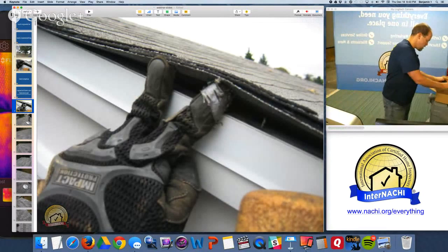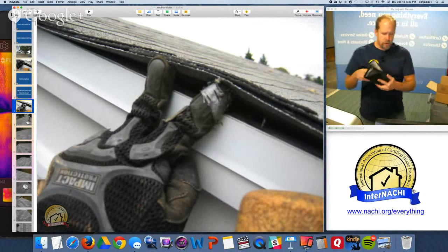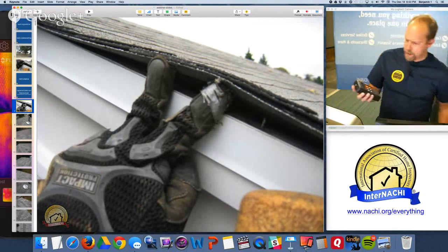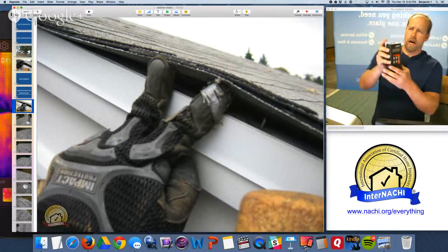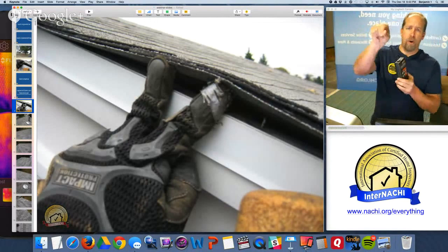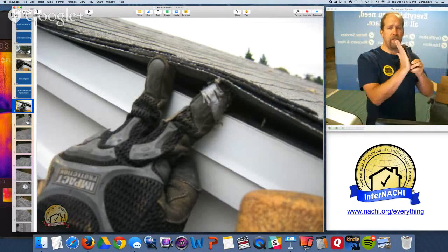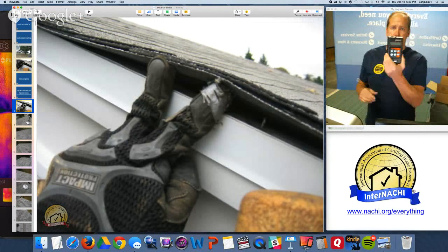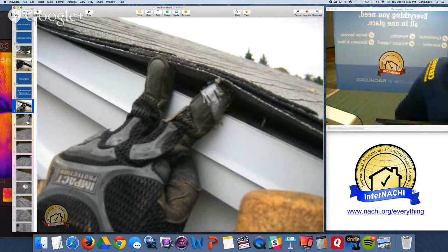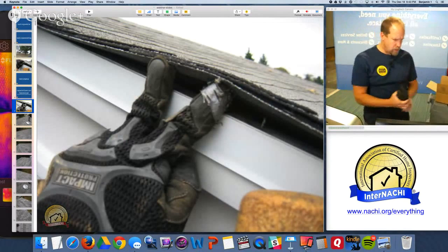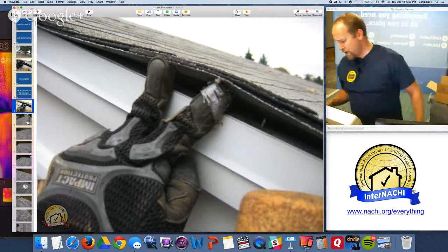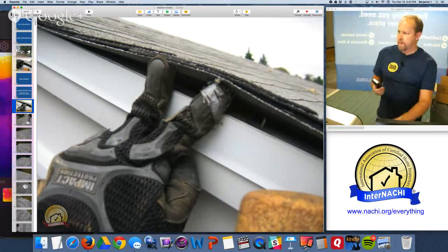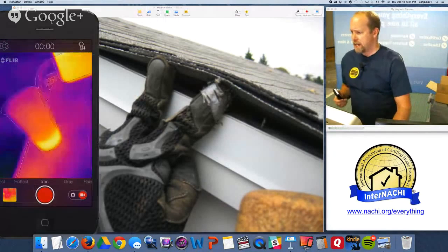Here's another tool that I use. It's not required by standards of practice, but it's a moisture meter. You can stick in your probes or non-invasive, and it beeps and gives an actual quantitative value for the moisture that you're looking for. And when I do an infrared scan, because I'm infrared certified, and that's a certification that International provides,